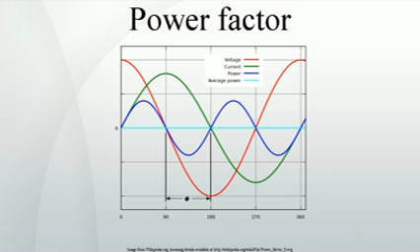At this point the power factor can be brought to near unity, using capacitors or inductors as required. This filter requires large-value high-current inductors, however, which are bulky and expensive. A passive PFC requires an inductor larger than the inductor in an active PFC, but costs less.